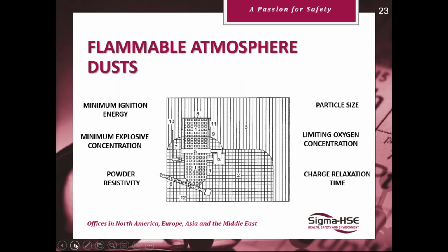Similar approach occurs for dusts. Particle size. Is it below 500 micron? If it is, then you've got potential for a flammable atmosphere. Limiting oxygen concentration again. Minimum explosive concentration. Are you working below it? As I said, beware here, because dusts are not homogeneous like gases and vapors.